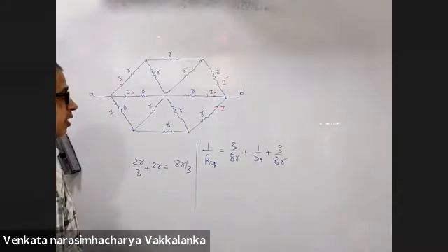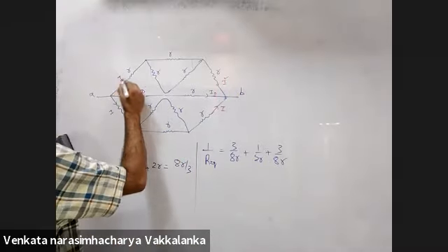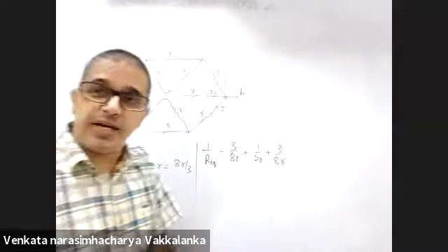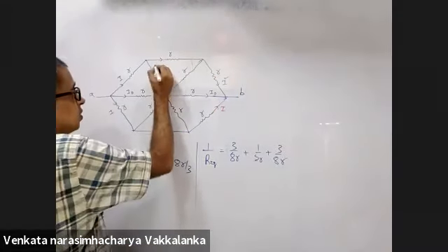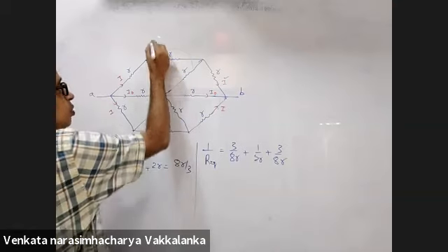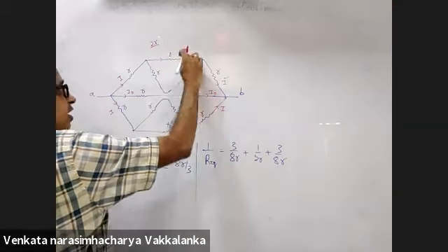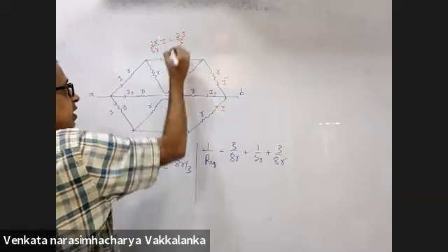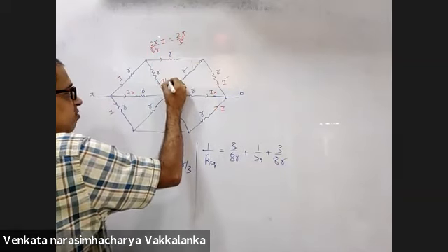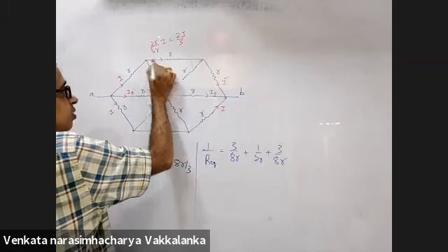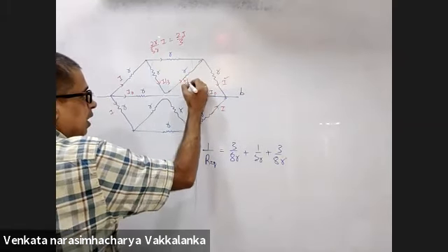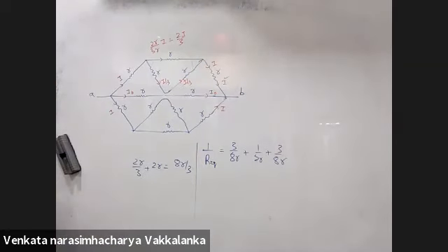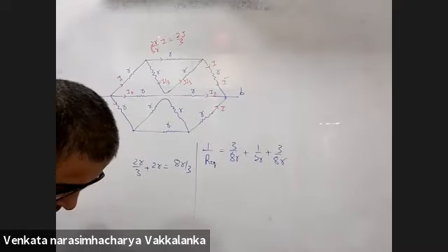Now look at the beauty. When you want to apply KVL, do you people remember how we split current into two branches, parallel branches? Resistance in the opposite branch, 2R divided by sum of both the resistors into the incoming current. So I will have I by 3 here, 2I by 3 going in this branch. I by 3 here, I will get back I here. Yes or no? Yes, sir.